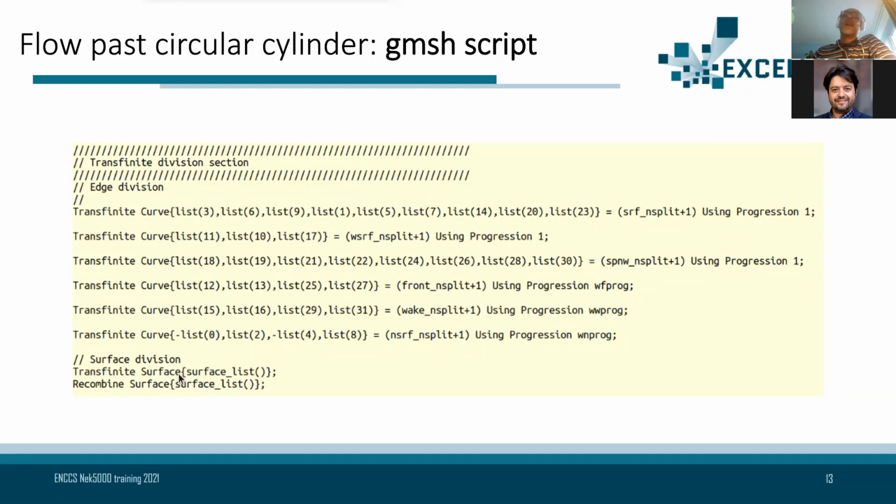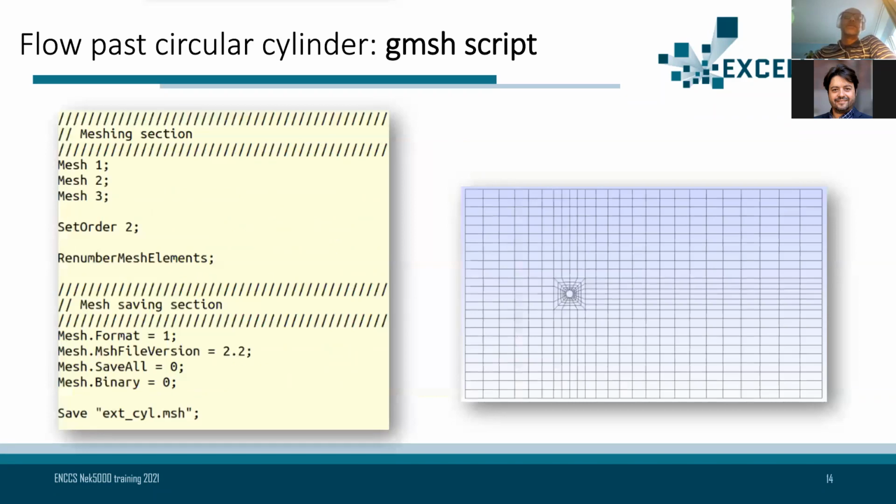The reason I'm doing this manually is that Gmsh provides a recombination algorithm for 2D domains, but there is no way of doing this properly in 3D. That is why I'm doing this even in 2D in the manual way, because at the end, if you do the 3D case, you have to do this manually. And meshing is one of the most problematic and time-consuming parts here.